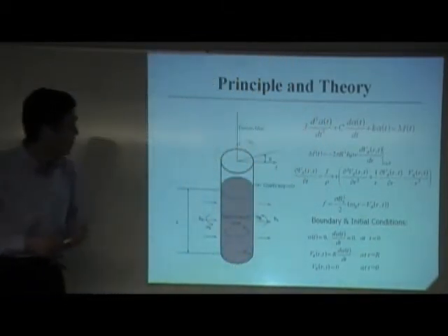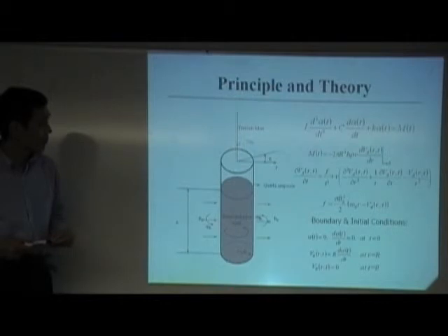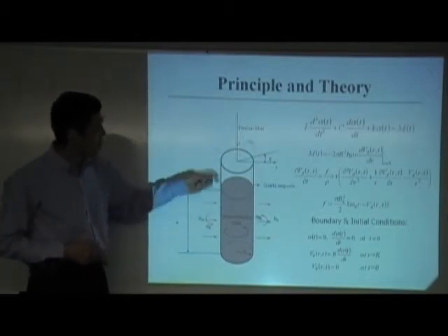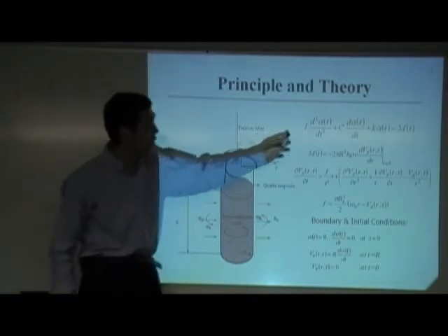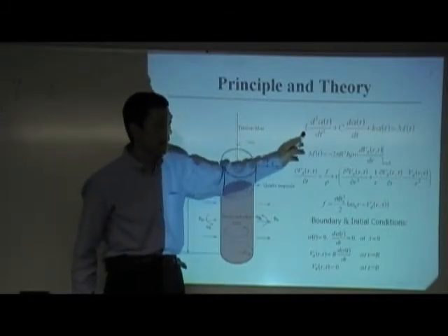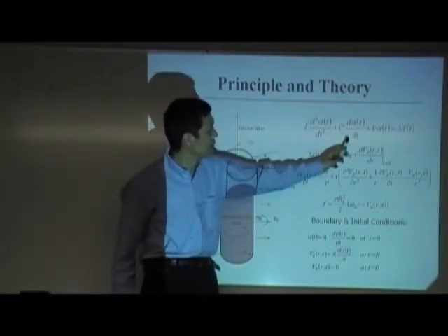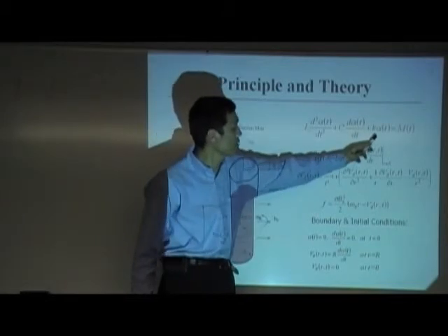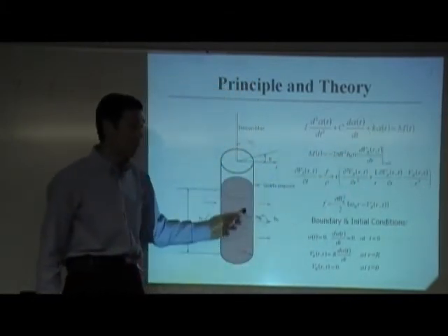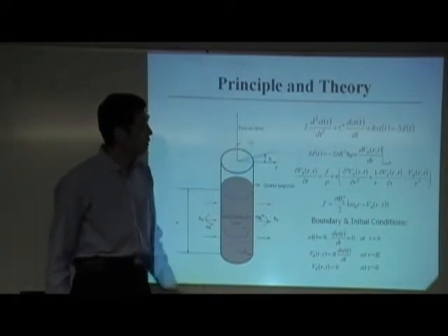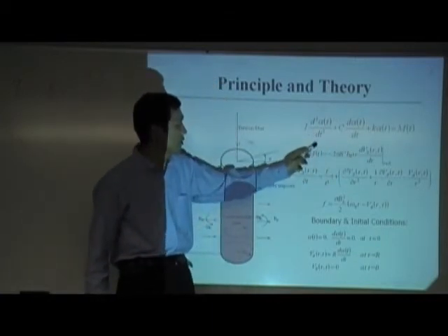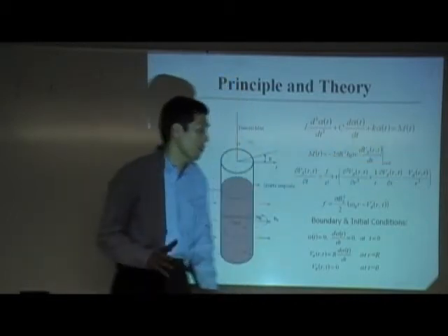So here is the model. Two systems: you have liquid, and you have a solid vessel. Looking at the solid, you have the solid vibration. This is the vibration equation for the solid vessel itself. This is basically angle, the moment of inertia times angular acceleration, and damping, and this is the spring constant of the rotational spring. And this is the force from the liquid itself. So that's a typical oscillation equation: you have a spring, you have damping, you have the angular acceleration term, and this is the external force.